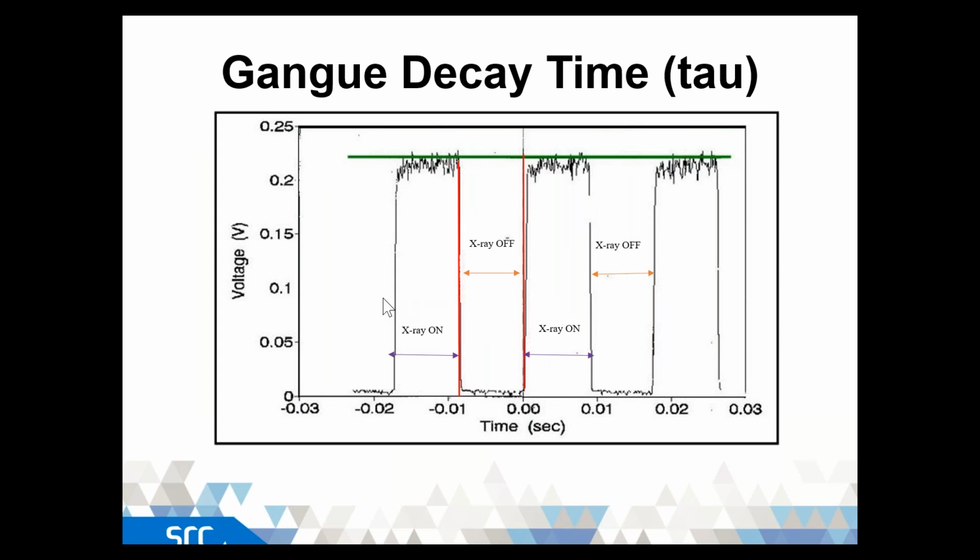The advantage you can use is you can also use that as a filtering mechanism, because that relates to your gangue material, where you turn your X-ray source on that gangue material and it'll be at peak intensity as soon as that X-ray source is applied, and you won't have to wait that certain amount of time to be able to detect that. So you can set up your algorithm to then detect that diamond based on that decay. And so rather than detecting it while the X-ray source is on, you wait for that half a second while that X-ray source is off to determine that luminescent property to then filter out any of the unwanted gangue material.